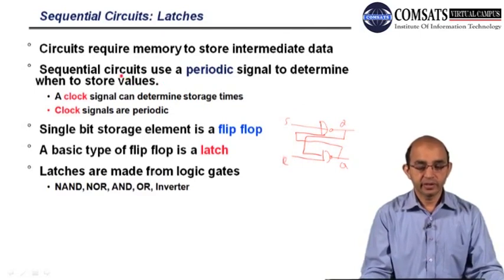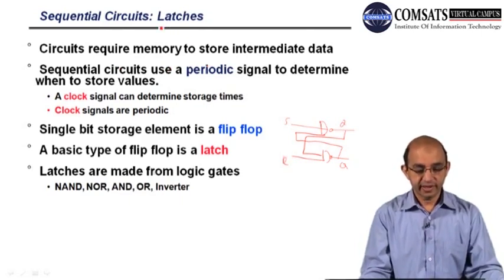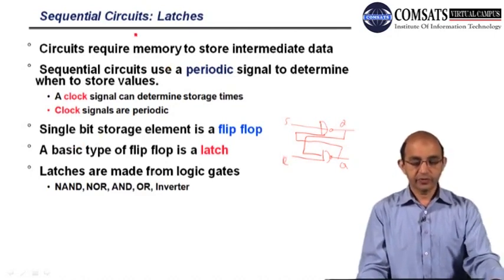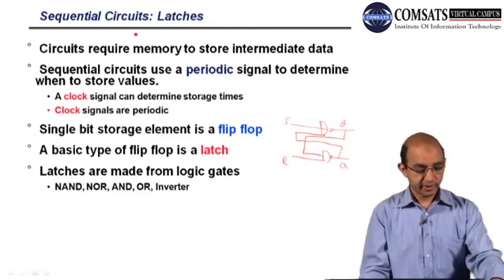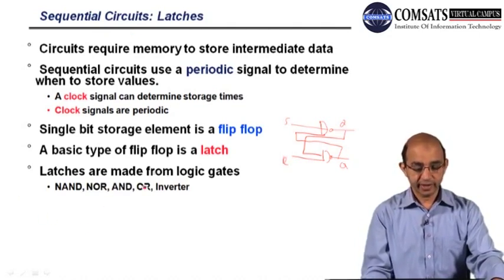We first started the sequential components by discussing latches. The latches are level sensitive, so they are only able to recognize the level. If we want edge sensitivity, the latches are not the right choice. We can have latches that can be made from NAND, NOR, AND, OR, inverter.